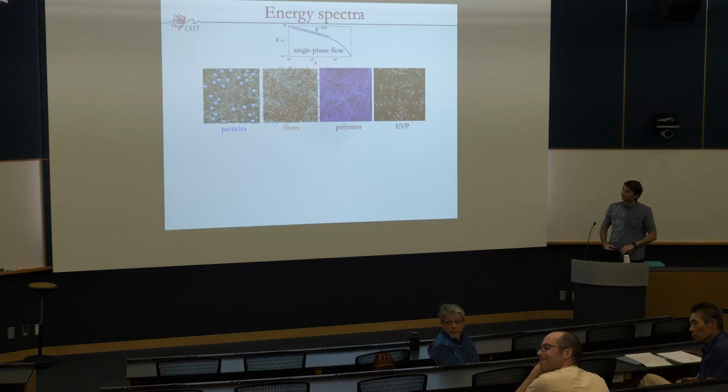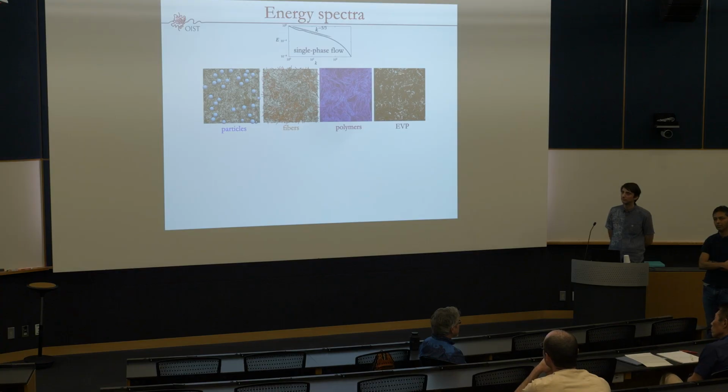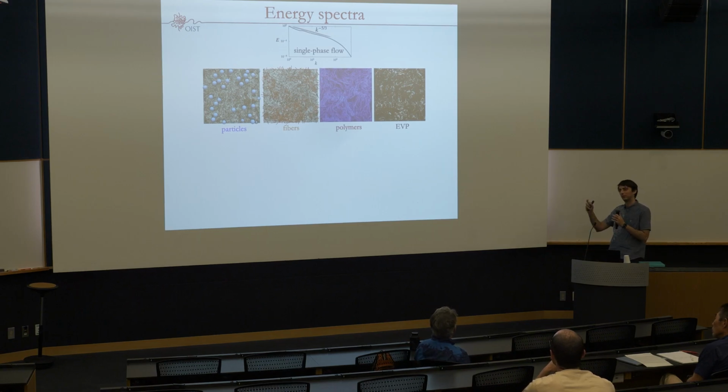I have a basic question. In this simulation for particles and the fibers, these are particle resolved simulations? Yeah. I didn't mention it directly, but most of what we do is that all the objects that you see are there and they affect the flow. So in technical words, yes, they are particle resolved, which is why we need this huge resolution. Most people, as maybe Pinaki mentioned, don't really put a particle, they just model it as a point particle, but we don't do that. What we do is a finite size object with its own shape, which interacts with the fluid.